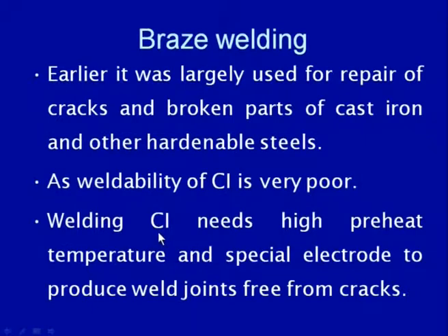Further, many times due to the size and shape, it becomes difficult to preheat the cast iron components to a very high temperature, and under those conditions it becomes very difficult to weld by the conventional arc welding processes. So, for the repair purpose under those conditions, and for repairing minor cracks, braze welding is found to be suitable.